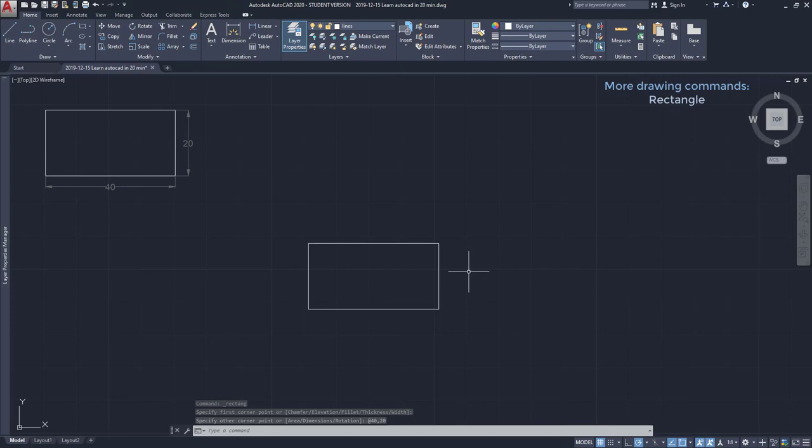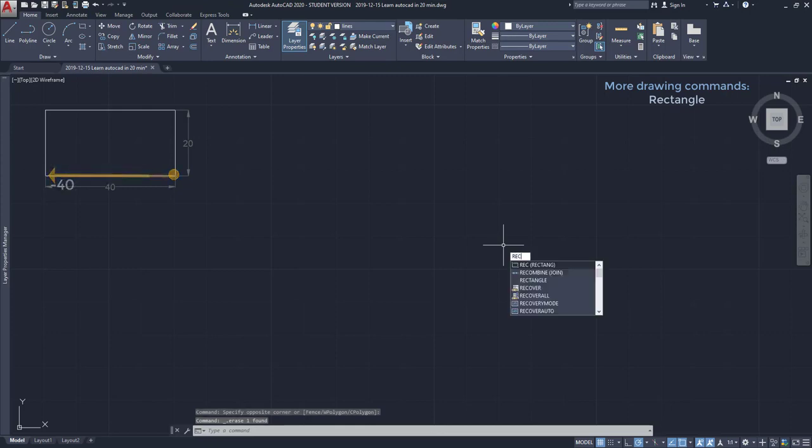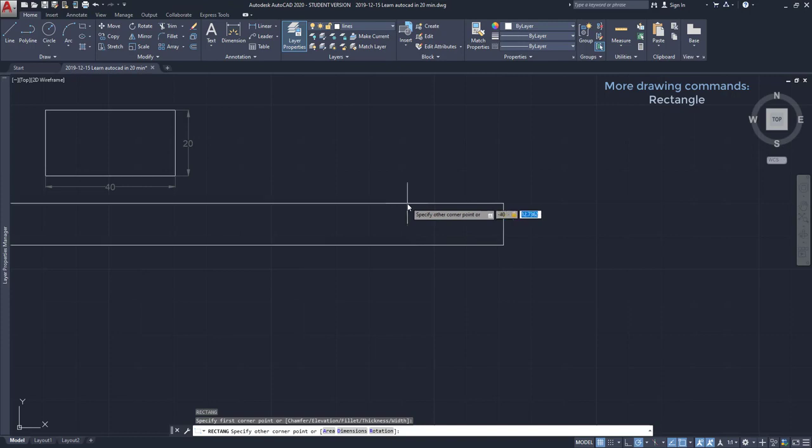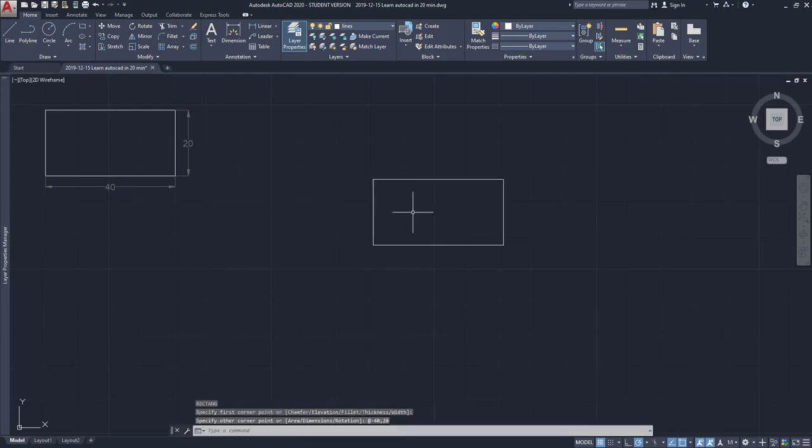However, as I still have to take into consideration the UCS coordinates, sometimes the values might be negative. Let's suppose I draw another rectangle but with the start point. The x coordinates would be -40. Click for the start point, then type -40, press Tab, and as the y coordinates are positive, I type 20. Here you have the result.